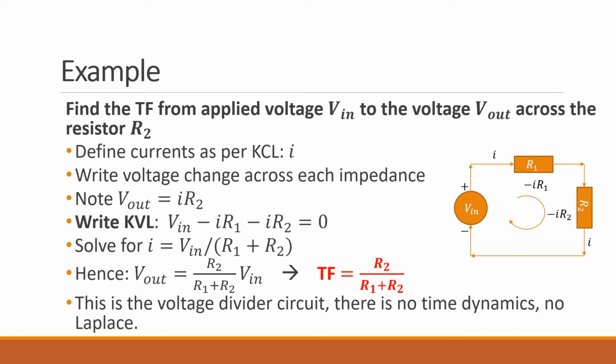By the way, this circuit is called the voltage divider circuit because the battery voltage Vin is divided into two parts across R1 and R2. We can use it to quickly reduce a given voltage, but it is not the best way for voltage conversion though, especially for high power circuits.